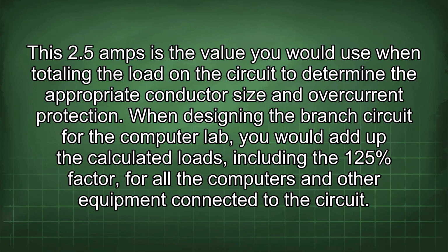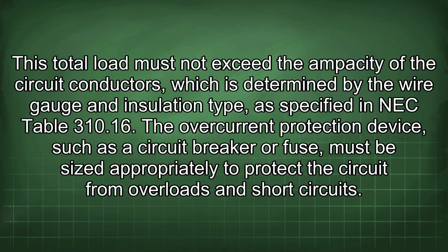When designing the branch circuit for the computer lab, you would add up the calculated loads, including the 125% factor for all the computers and other equipment connected to the circuit. This total load must not exceed the ampacity of the circuit conductors, which is determined by the wire gauge and insulation type, as specified in NEC Table 310.16. The overcurrent protection device, such as a circuit breaker or fuse, must be sized appropriately to protect the circuit from